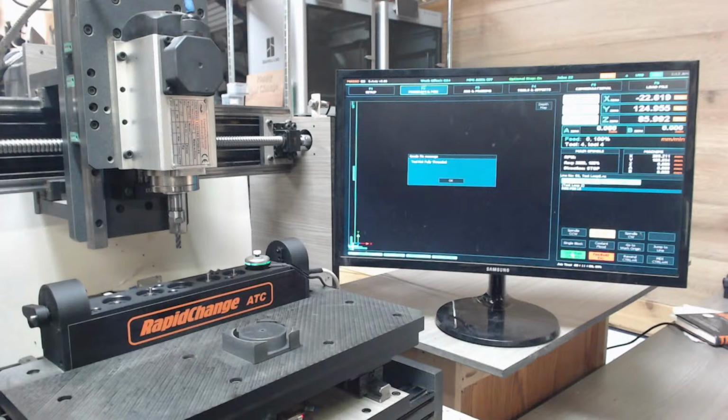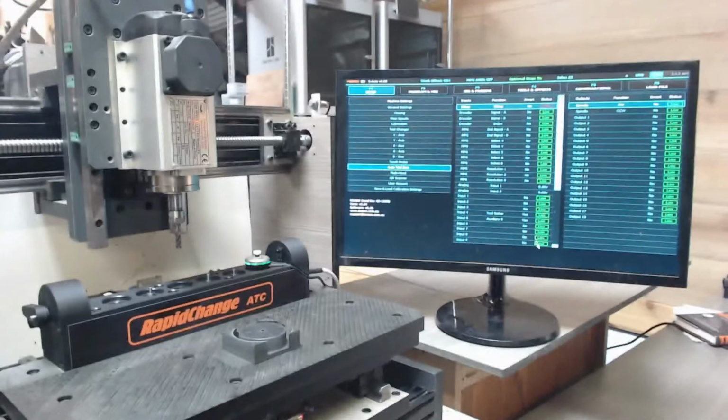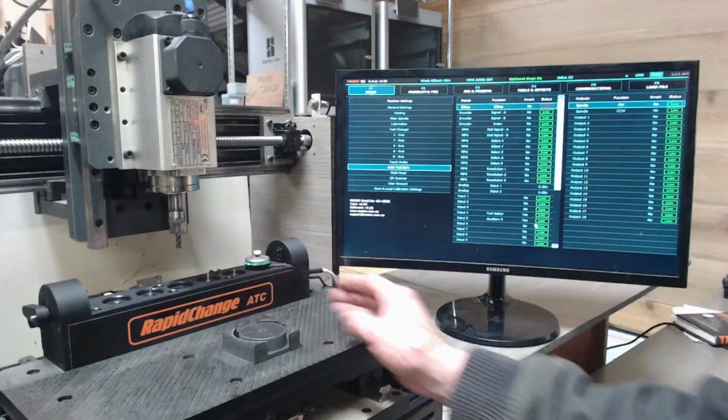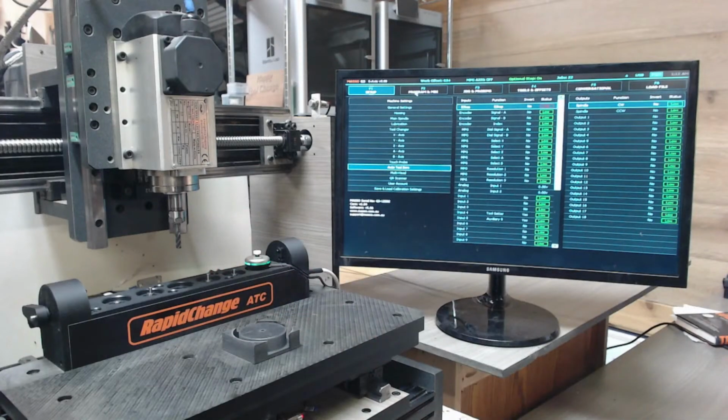Oh, look at this. We got a failure. It didn't read the sensor. So for some reason, if we look in the F1 setup now, auxiliary 5 is low, which is right. If I block the beam, it's high. So we got a false positive here